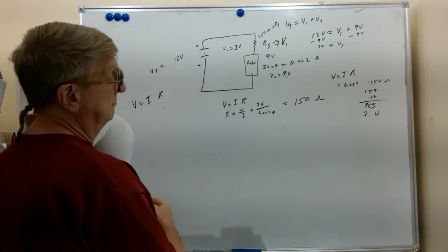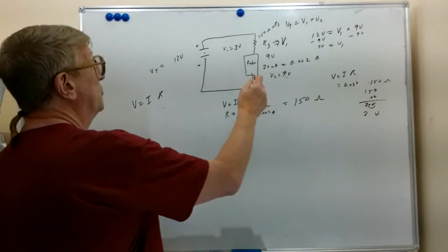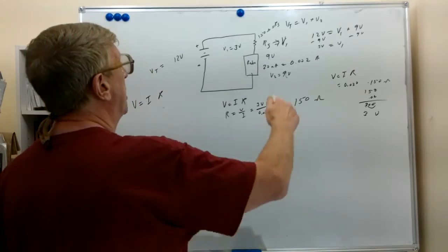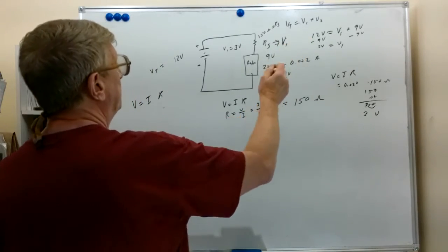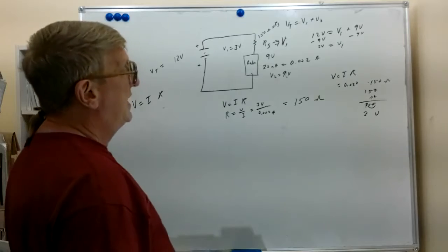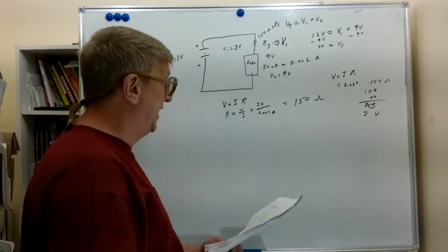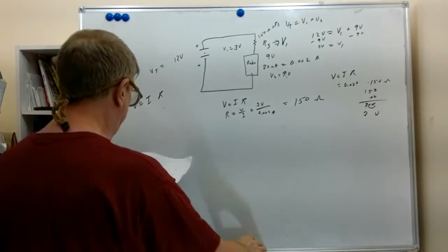So the current of the load is required. You need to know that to calculate a proper series drop-in resistor to run a load off a larger voltage. And of course you need to know the required voltage and the available voltage of your supply, so you figure out how much voltage you need to drop there.